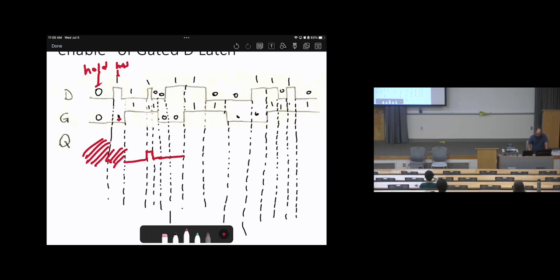Okay? Now in this status, G equals 1. Then copy the waveform of D. And here D equals 1. Then we will copy the waveform. So we will copy this. It will go to 1. Then it will go to 0. Now here in this scenario, G equals 0, then it will be on hold. G equals 0, it will be on hold. So for the total period, it will be on hold. Since it is 0, it will remain 0.